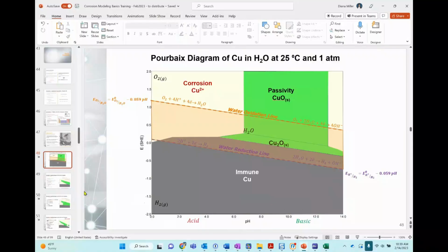Another one is a sacrificial anode. So in corrosion or in electrochemistry, if you have an anodic reaction, you need a cathodic reaction. So a sacrificial anode is like a big bar, let's say, it could be made out of zinc. That's what in boats they also put, these big pieces of zinc.